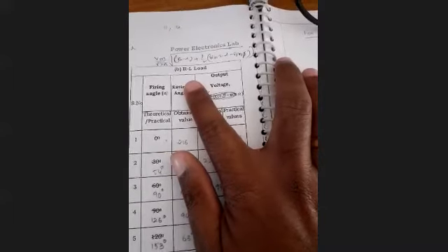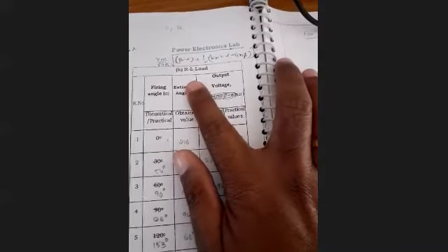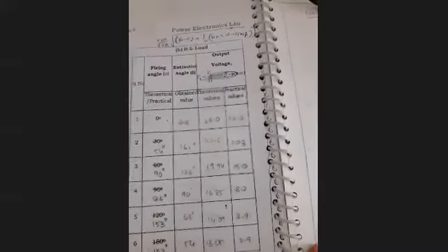In the case of theoretical values, we assume that the devices are ideal, with no drop across them, right? But in practice, you need to consider the drop across the devices. Similarly, you can calculate theoretical values in the case of RL load, and this expression is Vm by square root of 2 pi, times square root of beta minus alpha plus 1 by 2 sine 2 alpha minus sine 2 beta, where beta is the extinction angle, and we got it as almost 216 degrees, right?